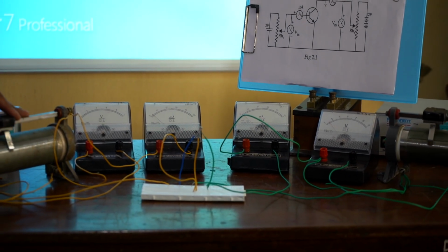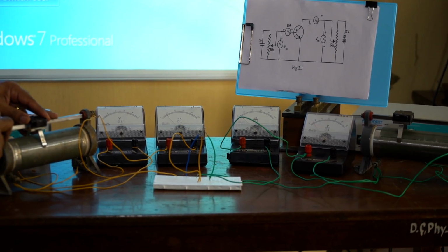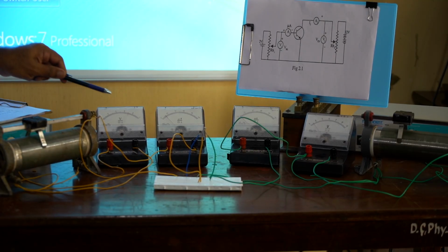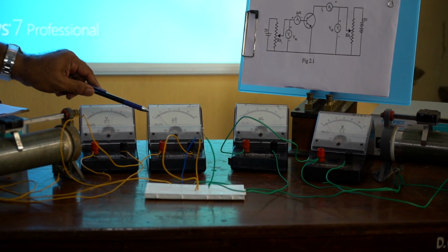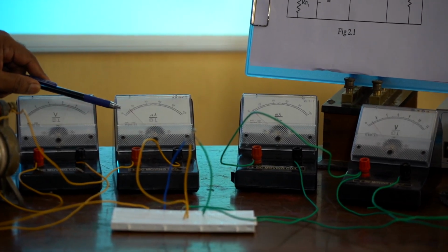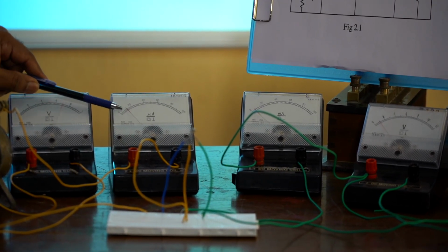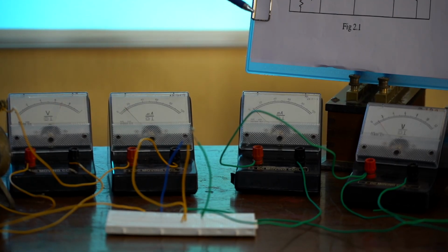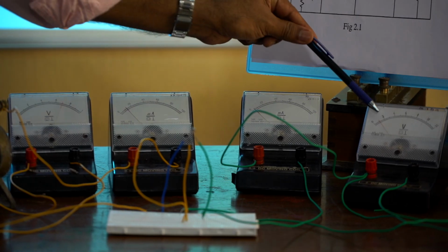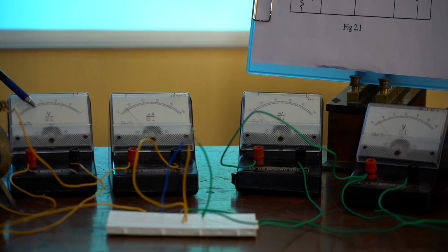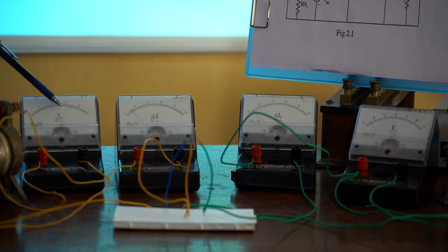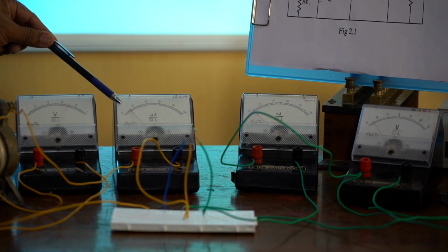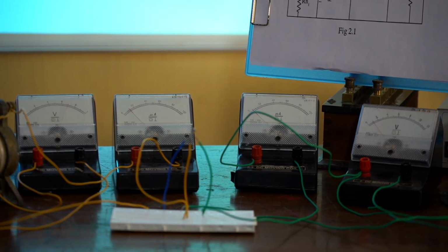Now when the voltage on the input side is say 0.7, what happens is that IB starts, and we get a particular value of IB. Now IB is equal to 10 microampere. Remember, VCB should be constant, that is 1 volt. VCB is 1 volt, the base emitter voltage is 0.7, and IB starts flowing: IB is equal to 10 microampere.